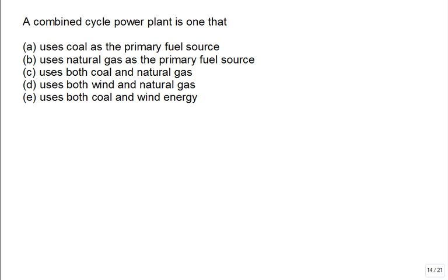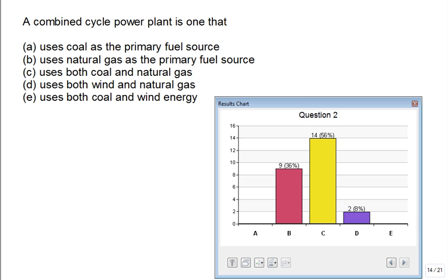And a combined cycle plant is one that, well, a combined cycle plant is combined in having a gas power cycle and a vapor power cycle. Typically, you burn natural gas in the gas turbines, still some hot, so you boil some water to make steam, to feed into the steam cycle to make electricity.